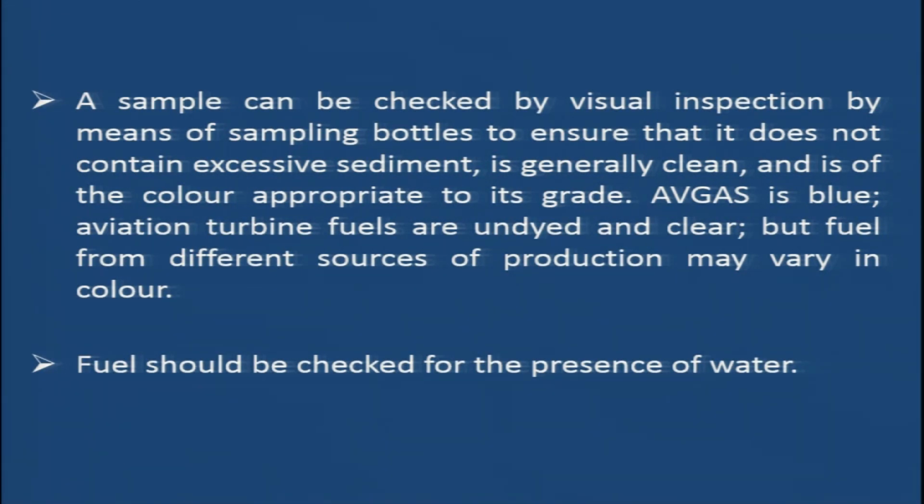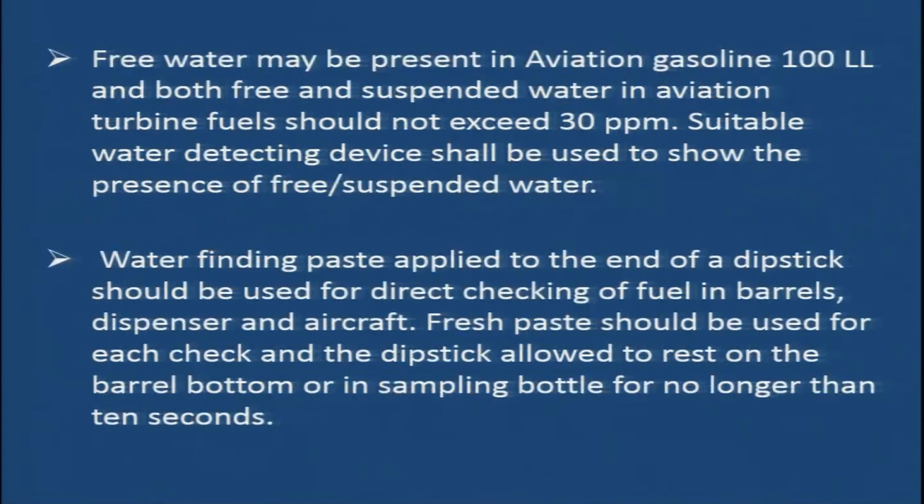During the sampling check, apart from the traces of sediment, we need to check the presence of water, and we need to check whether any cloudiness is there in the fuel. So, the fuel should be properly checked while taking the samples.